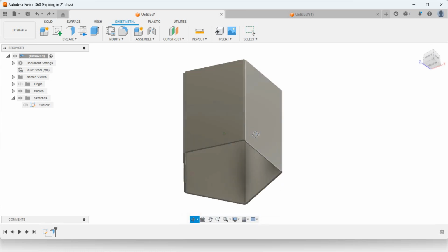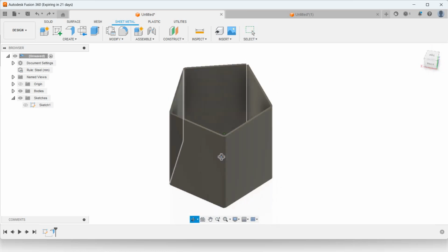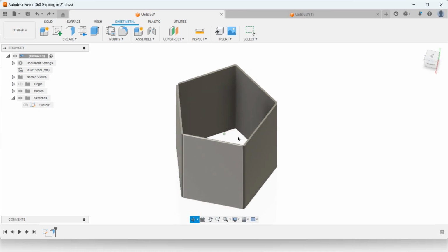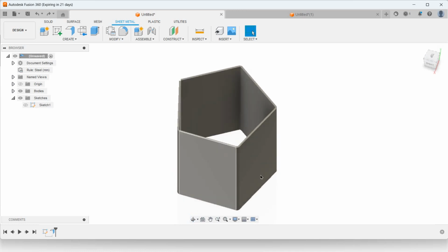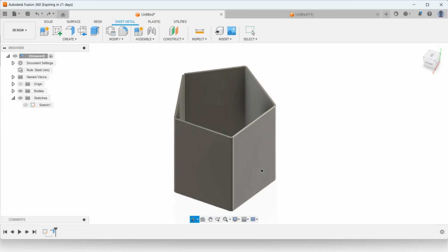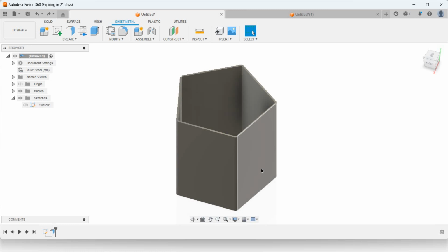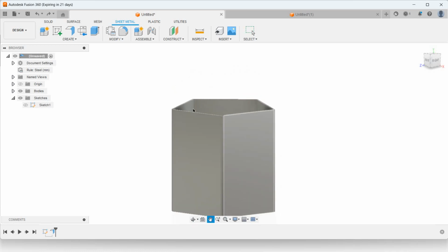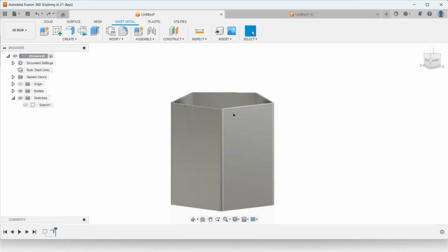We can see here there are 5 vertical rectangular faces, and here I have not drawn top face and bottom face because we have to draw development of lateral surfaces only. Lateral surfaces means vertical surfaces. We will not consider top surface and bottom surface of the prism. So here if you unfold this prism, then how it will look? That is nothing but development of lateral surfaces.